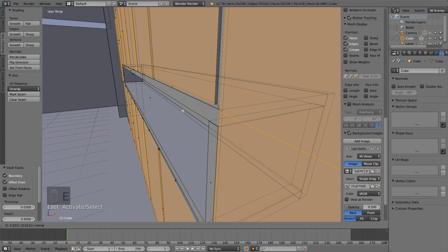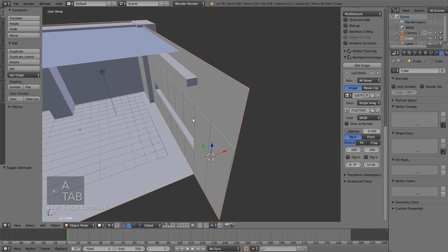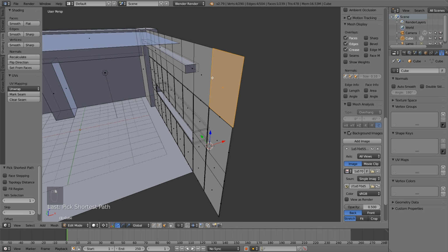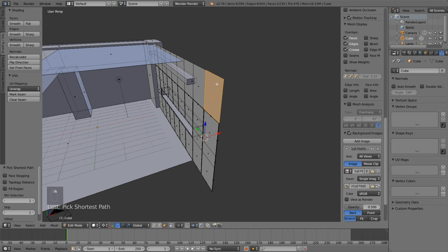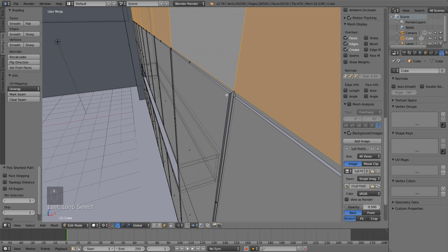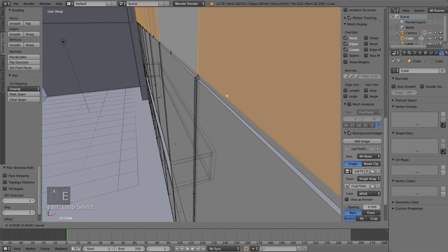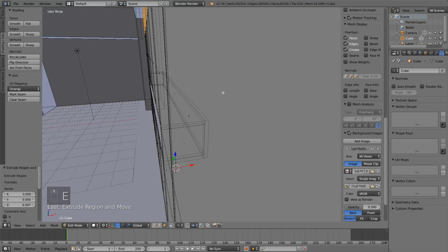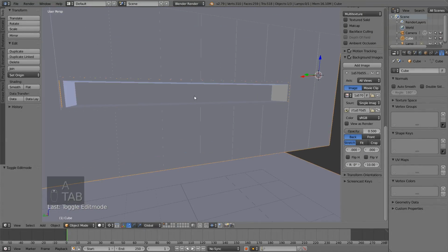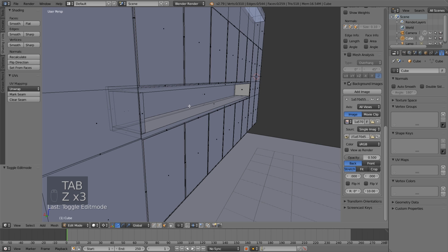So we have like these sort of panels coming out of the wall. All right, something like that. And that is how we do that. And that looks pretty good. And now the top row here should also come out a bit. So I'm going to go ahead and grab, holding Alt and just clicking the edge there, all those. And we'll extrude these out the same amount. So like that. Very cool. So we have that kind of pattern across the wall, adding some nice details.